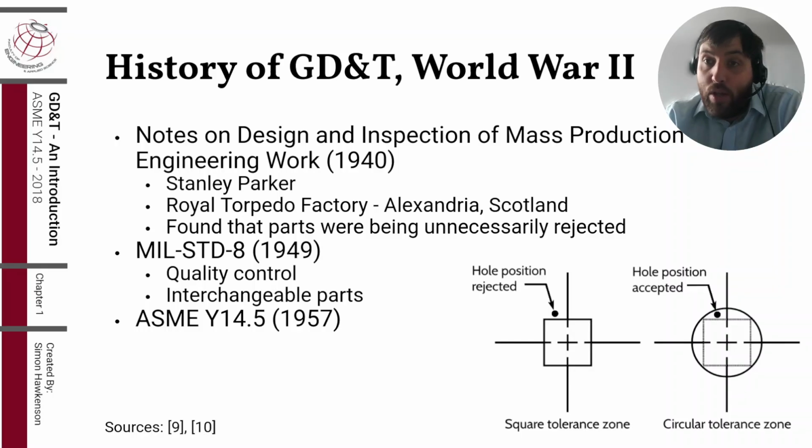But for tolerances such as ones that govern hole placement, the tolerance bounds that usually matter are circular. A hole center often needs to fall within a circular tolerance bound, but not a rectangular one. By restricting the tolerance to a square, the industry was needlessly rejecting parts that fell within the circumscribed circular zone.